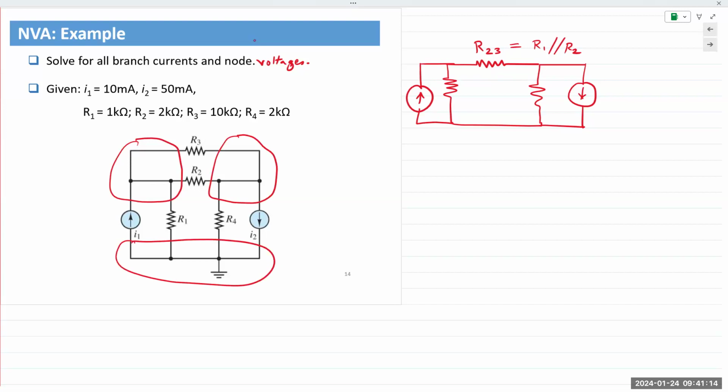Three. At first glance, the circuit schematic is drawn in such a way that we think that every dot is a node, which is quite normal. But when we take a look at the wires, if you look at the connections for each resistor, they're going to the exact same junction. And remember the fundamental point: it doesn't matter how long the wire is. It could be a dot, a short dash, a short line, or a very long line. They are all exactly the same.